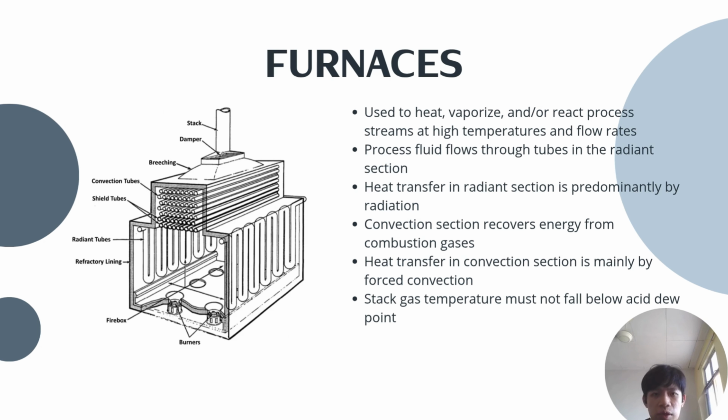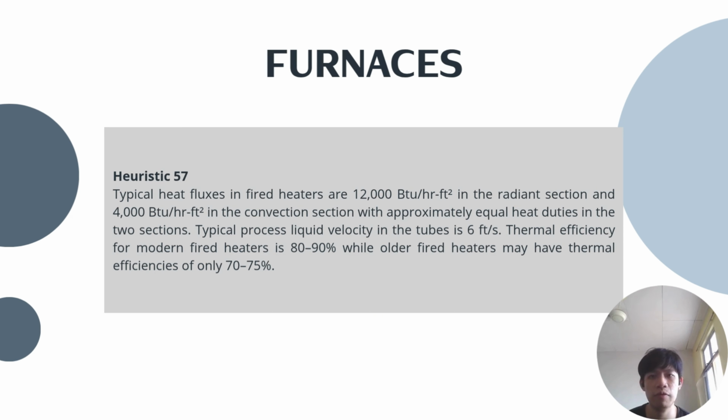The stack gas temperature must not fall below acid dew point. And then we have heuristic 57 for the furnaces. It provides the typical value for the heat fluxes, process liquid velocity, and the thermal efficiency.